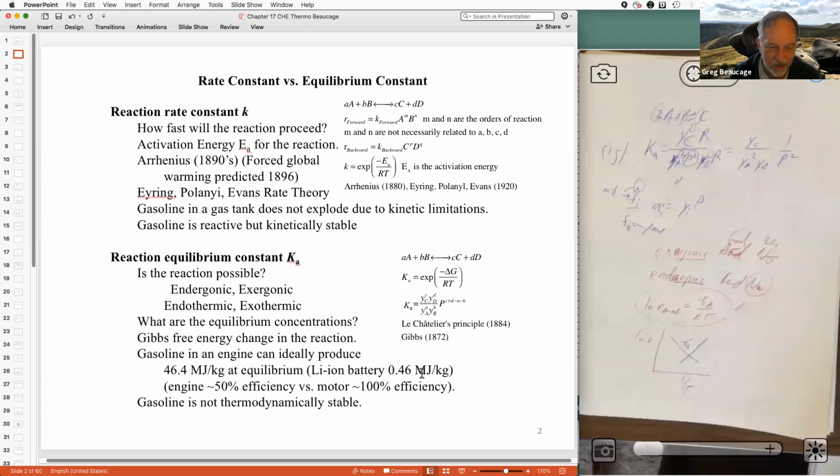So that's a big barrier to get over if you want to drive an electric car. Also, you can fill a tank up pretty fast, and filling up the battery takes a little bit of time. There have been improvements in that, but a factor of 100 is still a huge thing. It's mitigated a little because the car engine is 50% efficient and the electric motor is almost 100% efficient. So it's really still 50 times more. It's still a hurdle to get over.